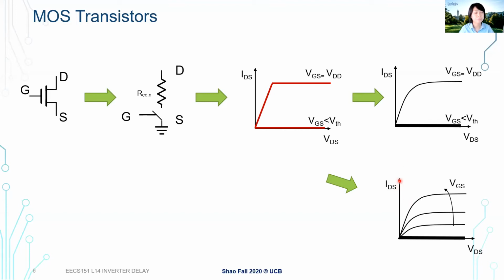One question. So I get that VGS sets how many electrons are there in the channel, which limits the amount of current that we can get. But wouldn't increasing the drain voltage create more potential difference? And since electrons want to go to higher potential, wouldn't they become faster? And if they become faster, wouldn't the current increase? Why does that not happen?